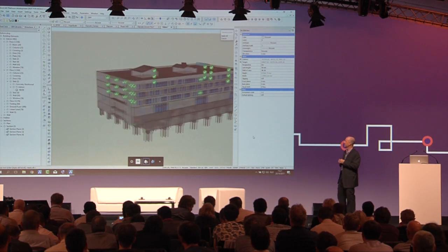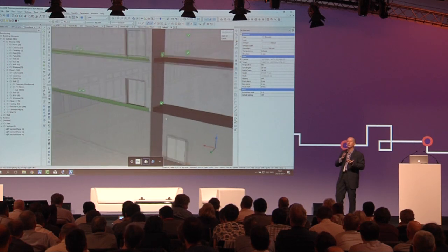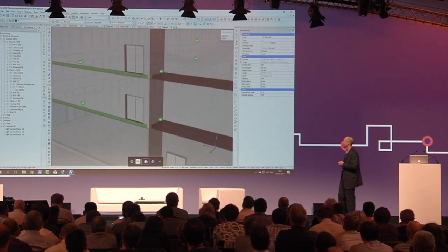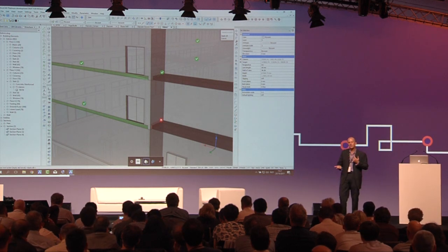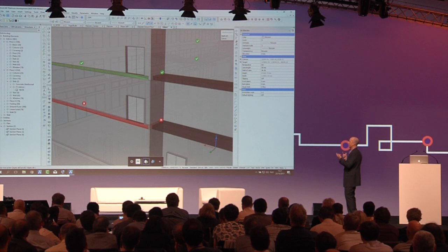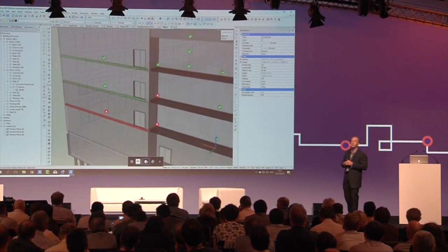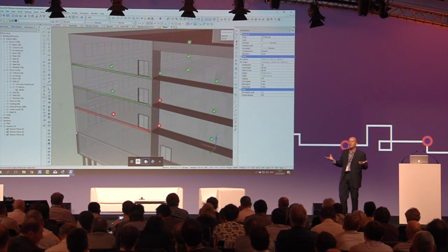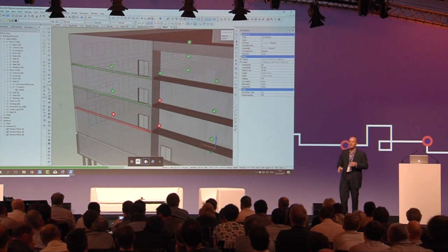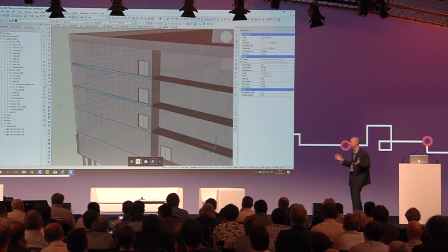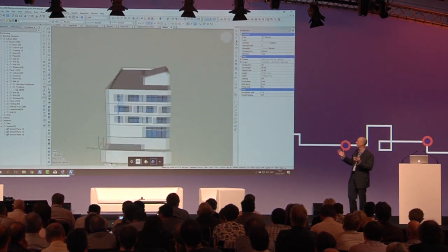So let's go to the back where the admin building meets the tower. Now, we know that a couple of those are going to be a different condition. So we can select them, and then it toggles them off. We can do that for the long face on that connection interface, and then we can do it on the floor above. By deselecting those, when we hit Apply All, those aren't going to be included, or they shouldn't be included.